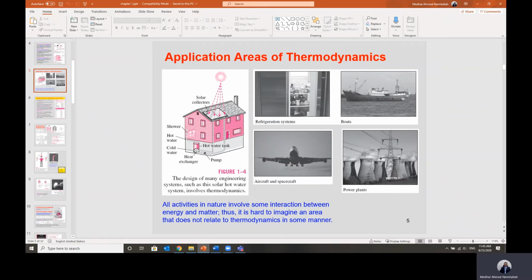So in this case, like the fridge at your home, we consume electrical power. Then we convert this electrical power into mechanical shaft power through an electric motor. This shaft power is used to drive a compressor to run the Freon inside the fridge, so that we can cool down the food in the food compartment. The mechanism is to convert electrical power, which is a kind of work, into a form of heat transfer so that we can absorb the heat from the food compartment.